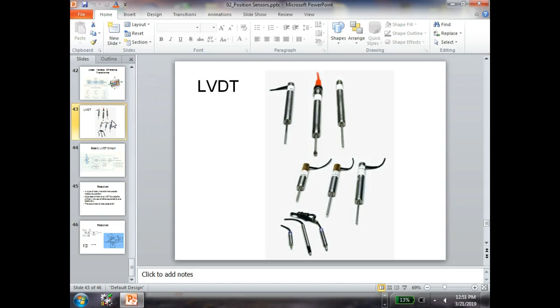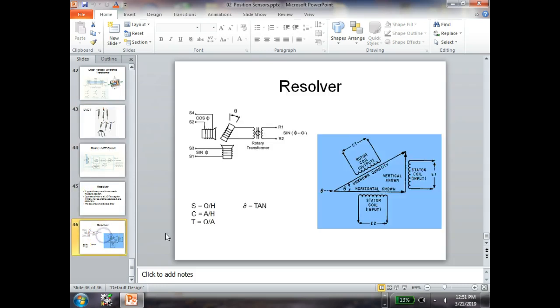So if I could come up with something that spins and we can indicate the direction, then we can eliminate the stroke problems. A resolver does almost exactly the same thing. It puts one sine wave in here and another sine wave in here. They're called a sine and a cosine. And then what they get out, the phase and the strength would indicate what? The amplitude would indicate the position, and the phase would indicate the direction. But this is not linear, this is rotary. That makes sense? Same principle. The rotary one is called a resolver, but it works on exactly the same principle. And the linear one is called a linear variable differential transformer, LVDT.